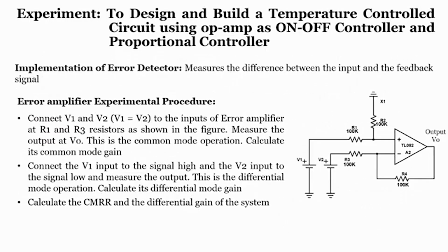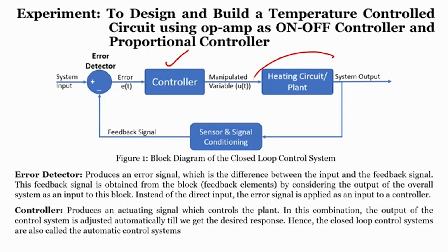Right. So, one thing is clear: the working of the op amp, the working of the heating circuit, and making use of a transistor and op amp, how we are going to generate heat. And it is clear the input voltage is 0 to 1, such that the maximum current will be in the safe zone, which is 10 amps. Because of that, it generates heat, and that heat is being sensed by a sensor, right.